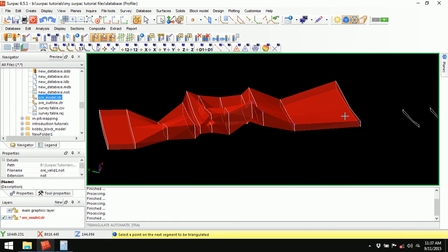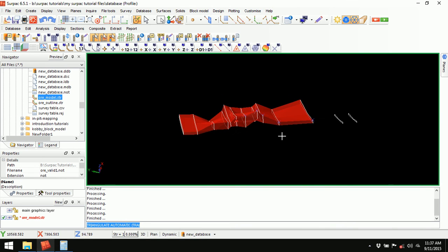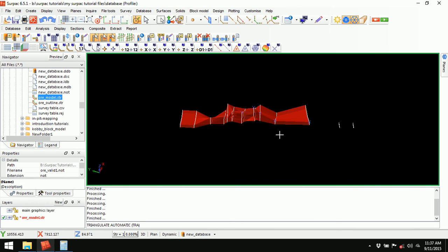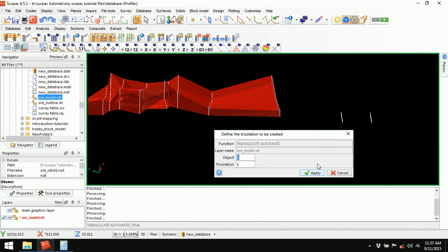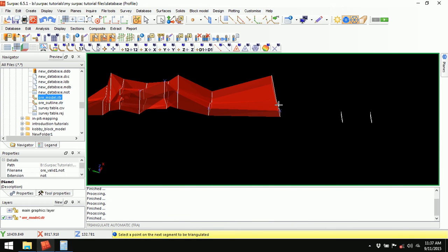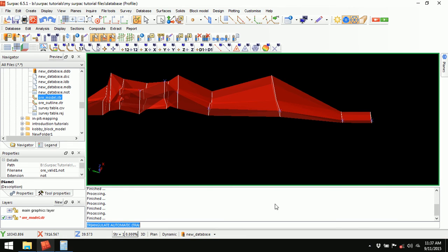I'll press escape. You can press F1 on the keyboard to freeze the function so that you can rotate your object in graphics. So I'll press escape. Okay, and I'll bring back the function again with the same parameters. This, join to this, and join to this. Excellent.